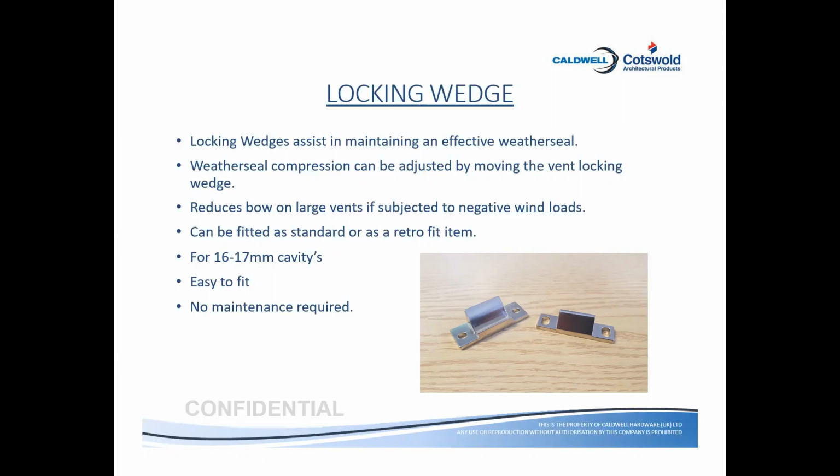Deformation in UPVC has its own calculation, and in aluminum the lengths are different. For wooden windows there are also a couple of charts. It is found that especially in aluminum windows, 2 to 3 percent deformation comes, so that the window gets twisted diagonally, or the outer sash of the window gets deformed.